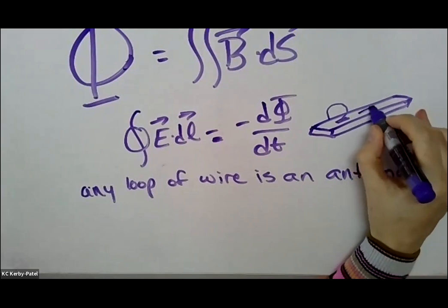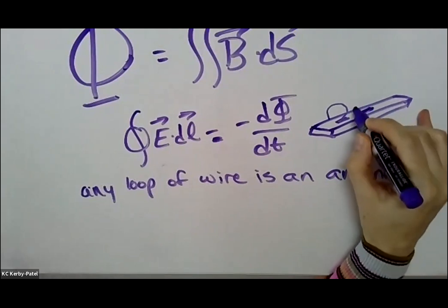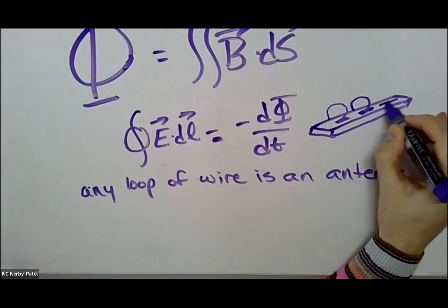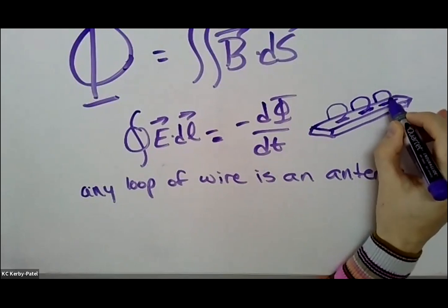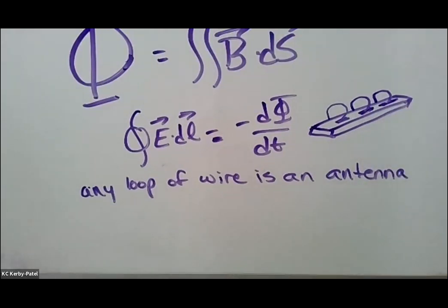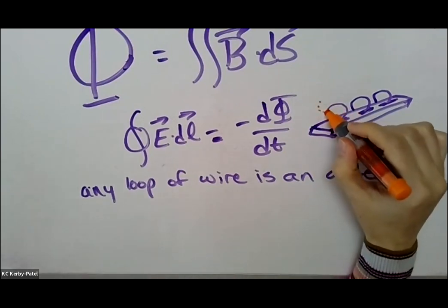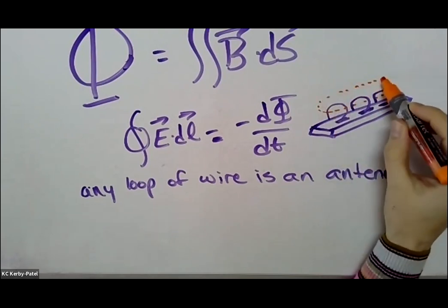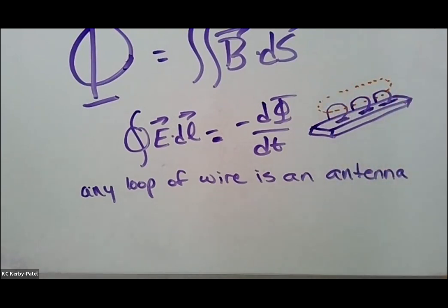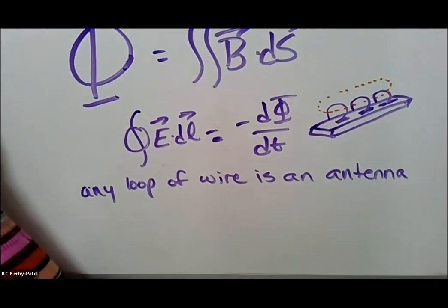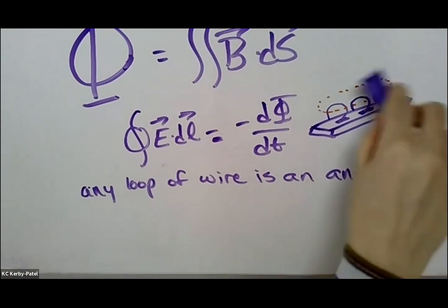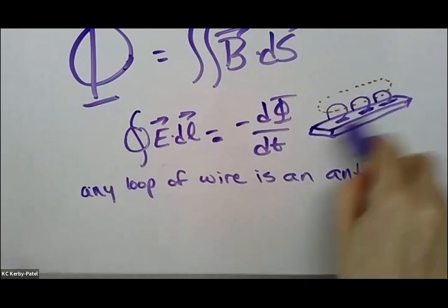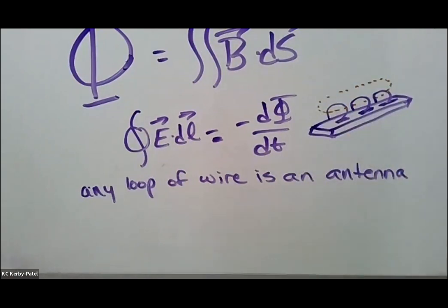And if you have more than one chip on your circuit, and maybe you have a couple of loops that stand up parallel to each other, these can share magnetic flux. And now you have a current pathway that is bypassing your circuit entirely. This is going to create an inductance that's just going to bypass chunks of your circuit.